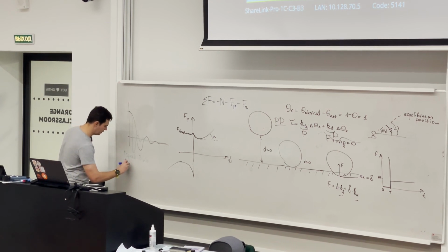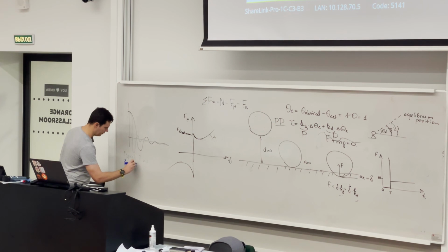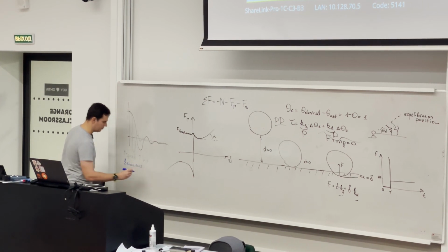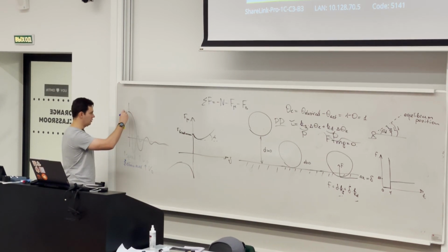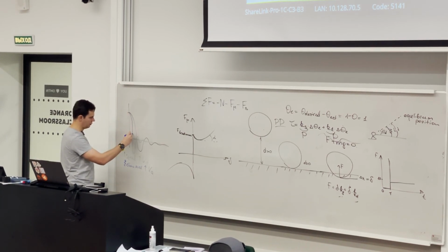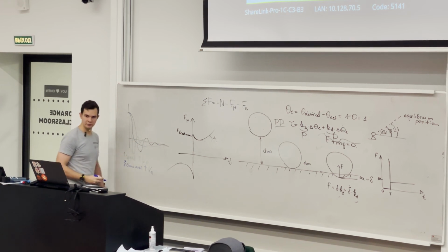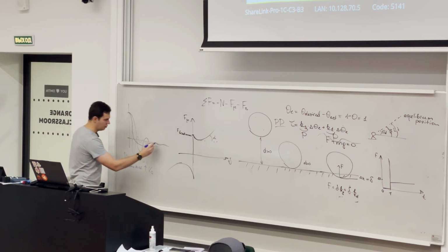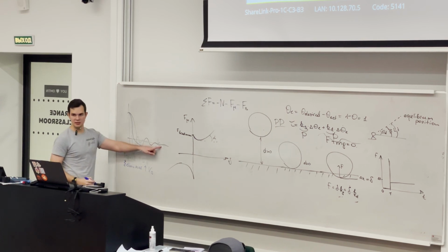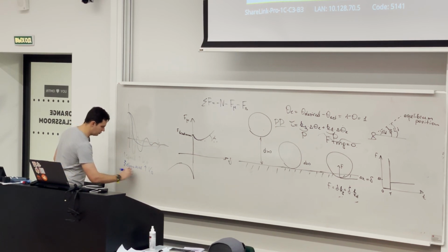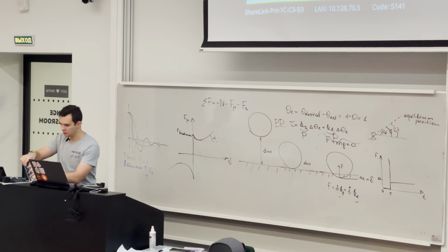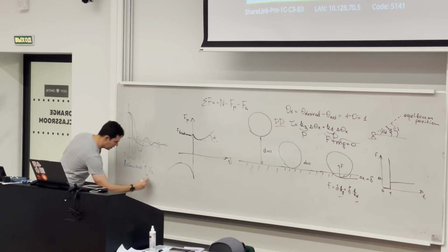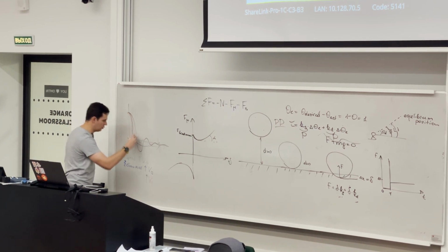So to eliminate the overshooting, we need to increase Kd, and it probably looks like this. And in order to get rid of steady state error, we need to increase the I component, Ki, and then it will look like this.